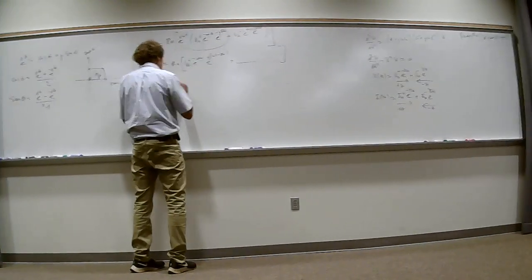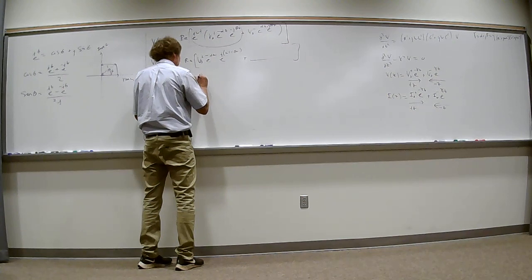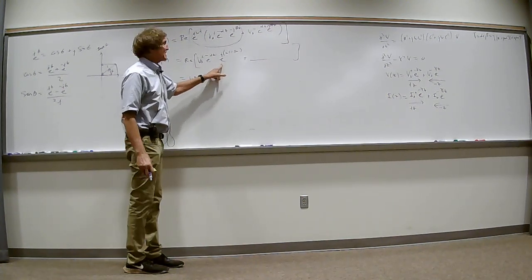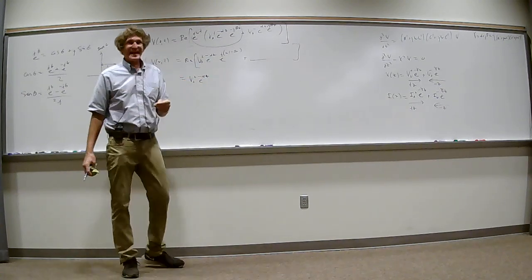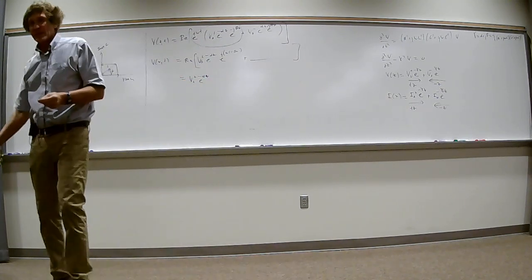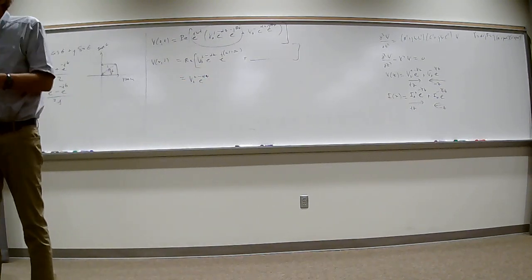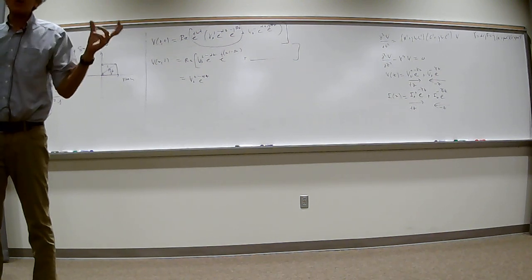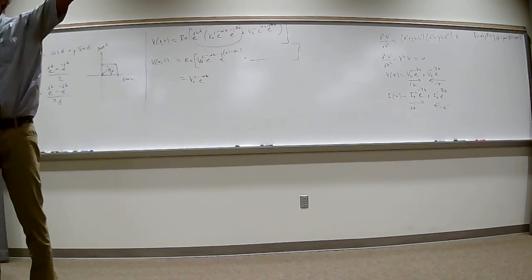So this is going to be v0 plus e to the minus alpha z. I did this last time. Now I've got that crazy e to the j omega t minus beta z. That's an angle. That's like that theta. That would be cosine of omega t minus beta z, right? Plus j sine of omega t minus beta z. Does everybody follow me on that? The real part is just the cosine. How many see this? All right.